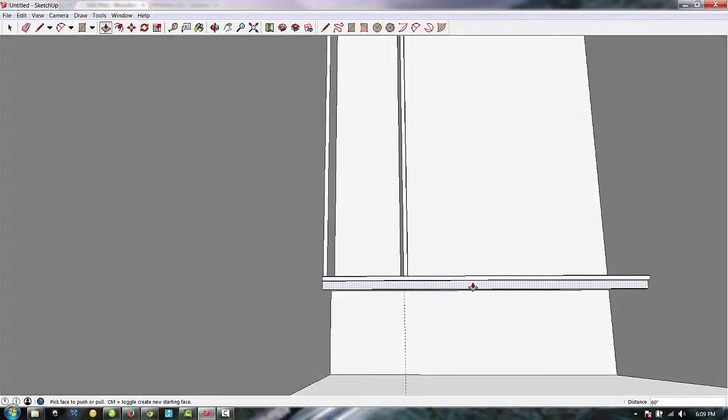One thing that I know we're going to do, we're going to go up and split the difference to create an upper bench. In my case, I know we're going to be 9 inches high on the upper side. So I'll just type 9 and hit enter for my guideline. And then again, the rectangle tool, draw my rectangle.